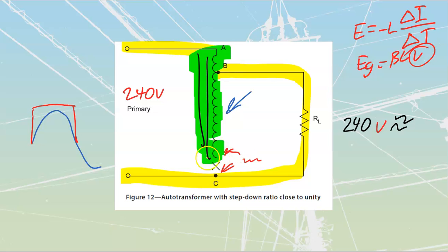Be careful with them. This is not a danger so much in and of itself, the way that the previous one was. This load is probably not going to blow up, having 240 volts over top of a 208 volt one, but it's going to run a bit hot, might get a little bit funky in its operation. The danger is always going to be to the person that's coming in to find out why the load has gone funky, and that's going to be you as an electrician. All right, that is Learn Test 13.